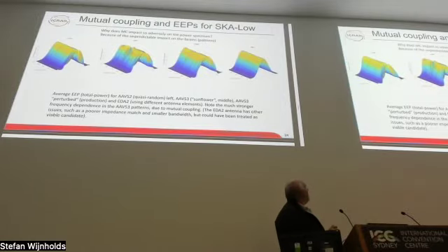This is more dramatically evident on this picture over here. What you're seeing here are average beams as a function of elevation angle against frequency for the AAVS2, the AAVS3, and the AAVS with the production version, compared over there on the end to the EDA2, which was an array built largely under Randall's guidance, using MWA elements on an SKA type layout. So this looks very attractive. The MWA has some other issues, and they relate to antenna input impedance, but it wasn't perhaps given as much attention as it could have been. This is very problematic. We predicted this effect beforehand, and it was actually measured very shortly afterwards.